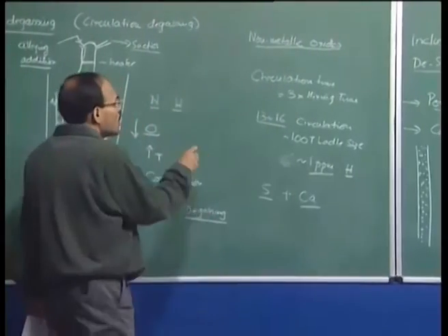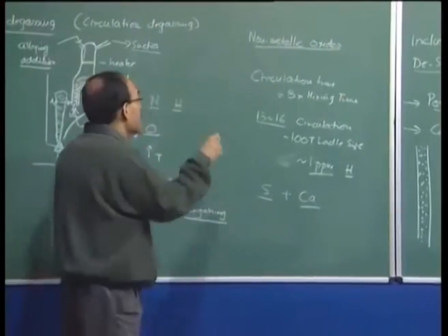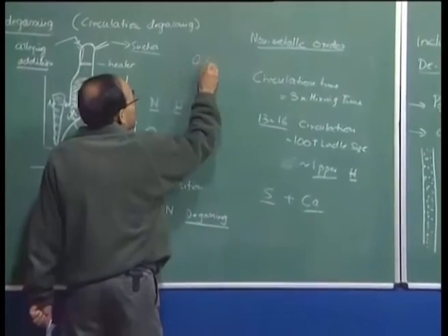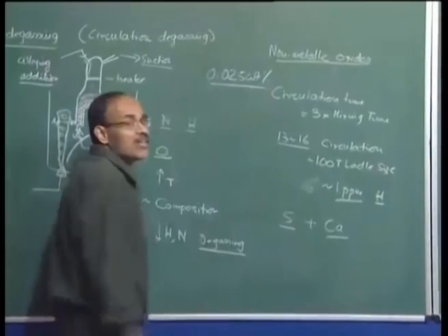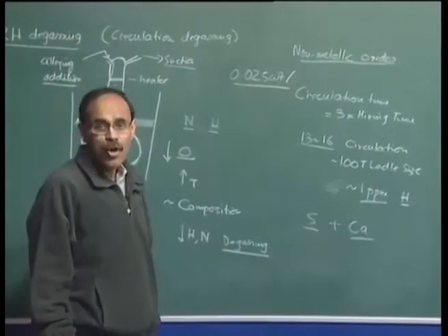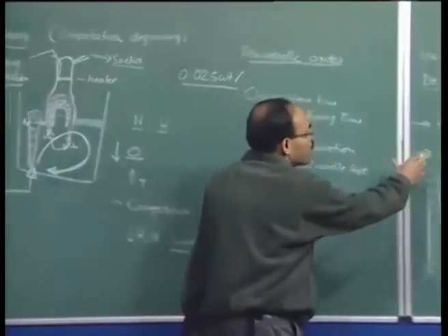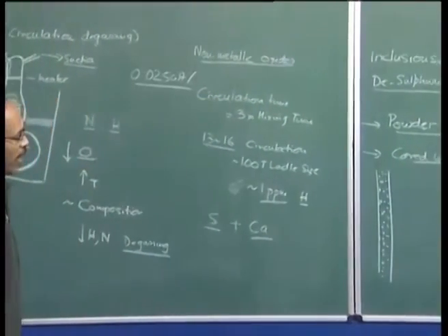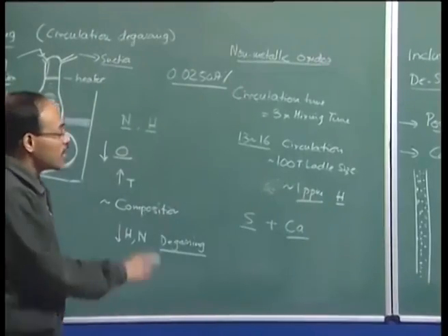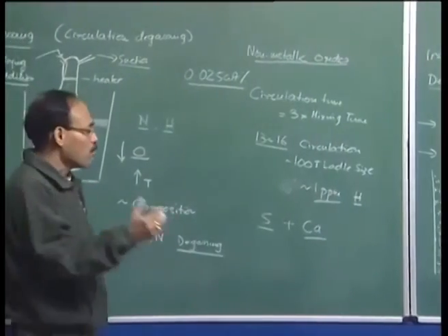And also, even if you can increase the contact time, the solubility of calcium in steel is roughly about 0.05 weight percent. As a result, under steelmaking conditions, although injection of calcium has many advantages in terms of inclusion morphology, control and modification, it is going to be a highly expensive affair, because the solubility is less.